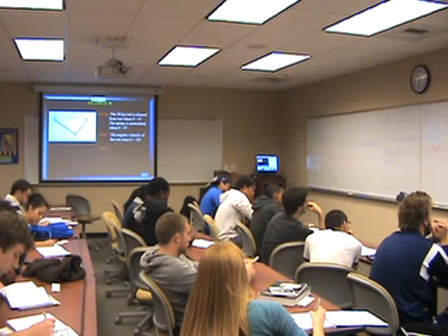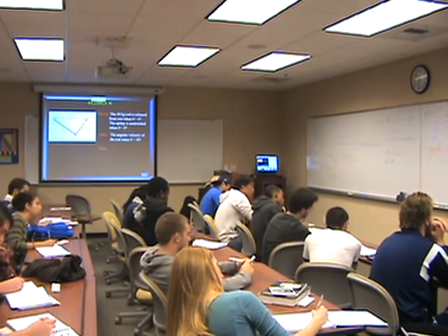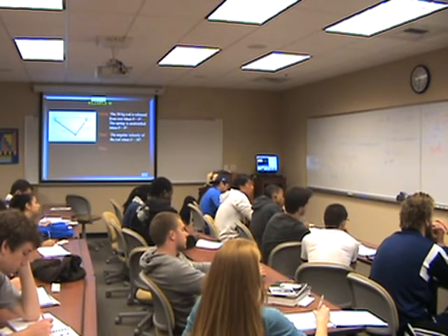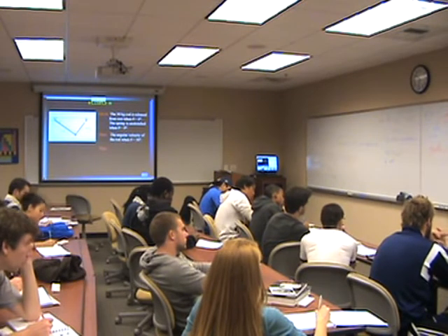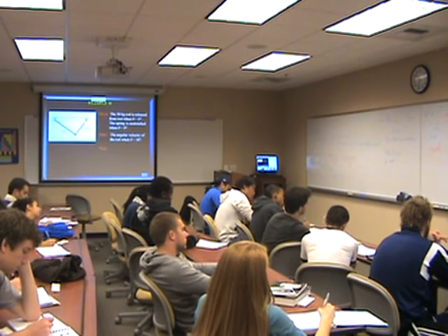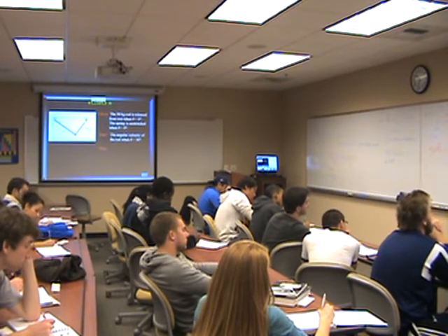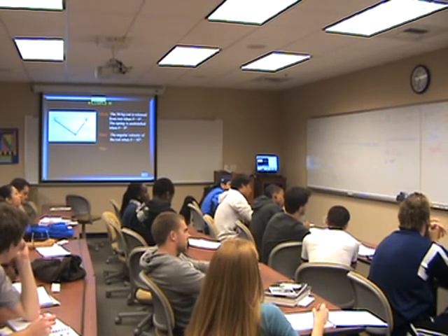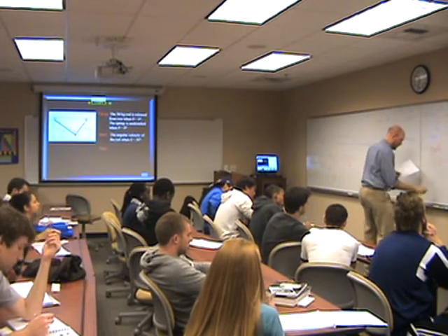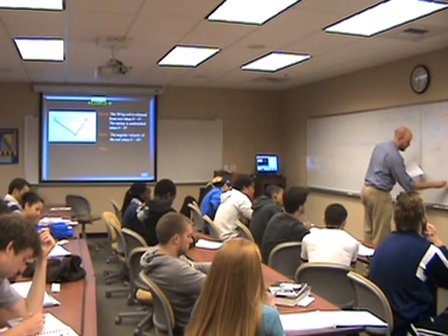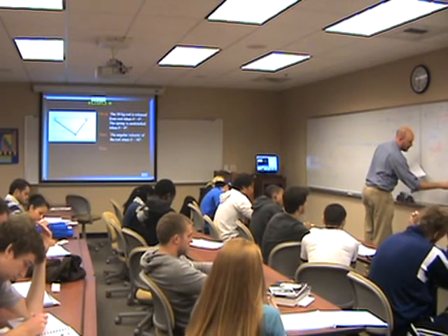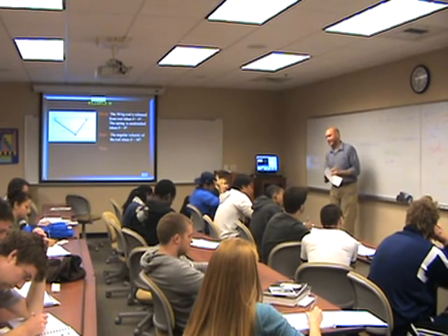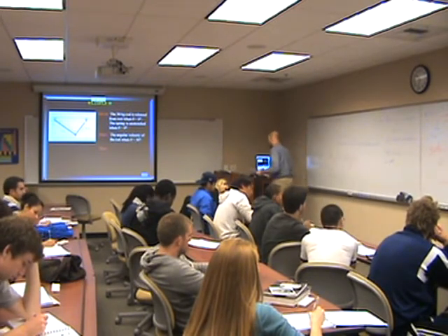Plus potential energy from our spring, which is 1/2 k s squared. k is 80 newtons per meter, times s squared, 0.527 meters squared. And that's all equal to 0. So from that we can calculate that omega is equal to 2.97 radians per second, if we plug it into our calculator, or MATLAB, or Excel.